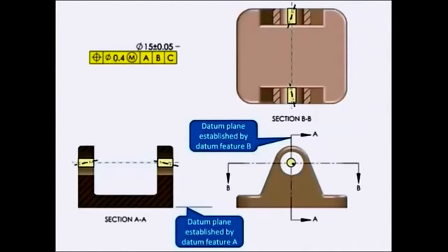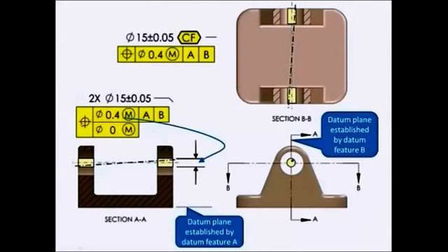By adding a composite tolerance or using the continuous feature symbol, either one would work, but we were going to focus on composite tolerancing. So by using composite tolerancing, which means you have one symbol but multiple segments or multiple tolerances, we were able to keep the two holes in line. So this is saying the two holes have to be in position within 0 if they're made at their smallest size. As they get bigger, they can misalign a little bit. But let's say I was assembling a shaft in here, that would assure assemblability. So that was in our first tip.